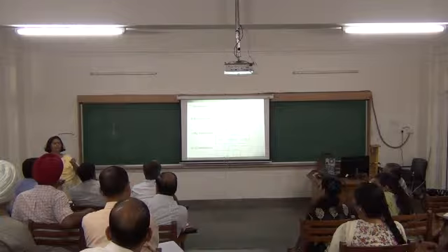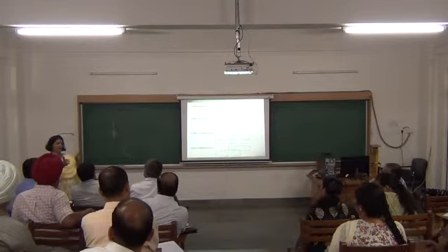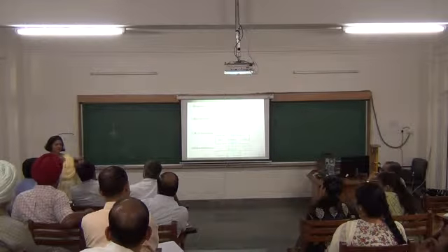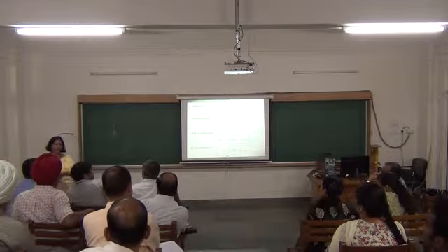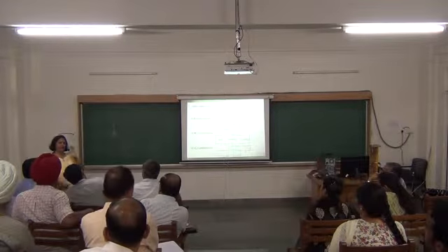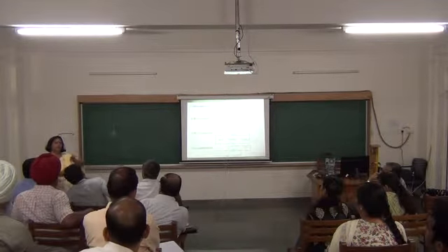That will depend on this total. Because you have a resistance R and you are putting something small in parallel, the total Thevenin equivalent will still go to a very, very small value. Not very small, it will become very small. So you always have to look at the Thevenin equivalent between those points.